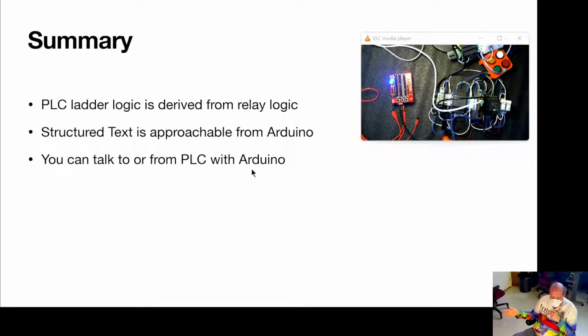I described to you how PLC ladder logic is derived from relay logic and what that looks like, and how it's not your only programming option for PLCs. If you pay attention to what PLC you're purchasing, you can program it in structured text, which works very similar to what you're used to in Arduino, with the same kind of control flow and structure, but you can map variables to inputs and other devices to expand your communication.